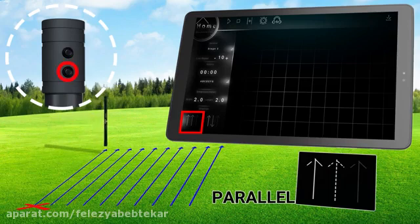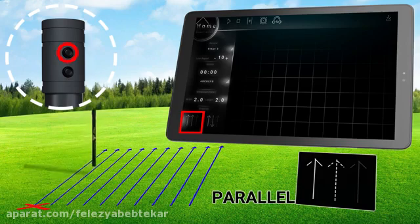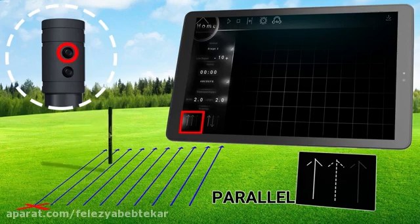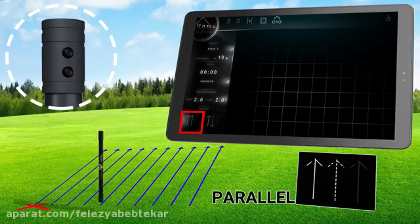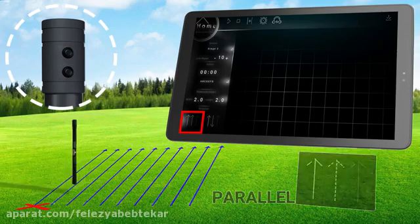Then we have to specify the type of scan direction. In unique scan mode, there are 2 types of directions called parallel and zigzag. The selection of each of these 2 types determines how we navigate to perform the scan. As you can see in the video, in the parallel mode, the scan is done in one direction, that is, when the scan is completed, we go to the beginning of the next line and continue the scan. In other words, the scan is always done in one direction.